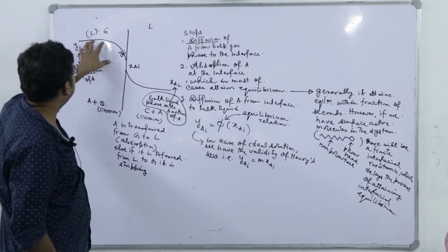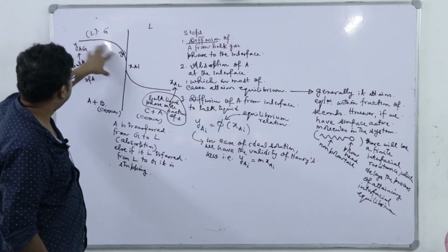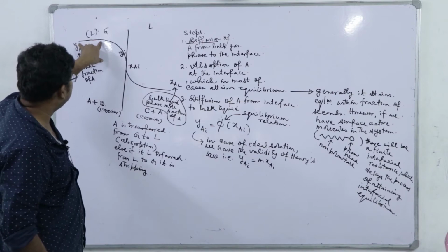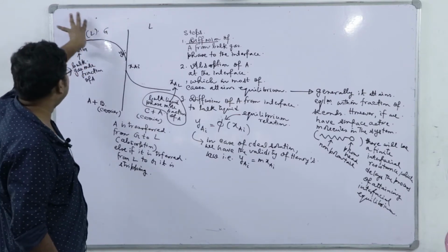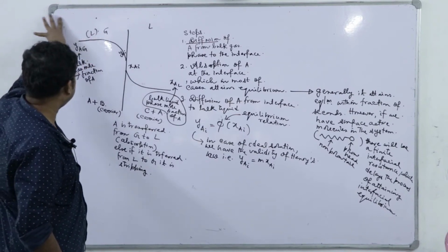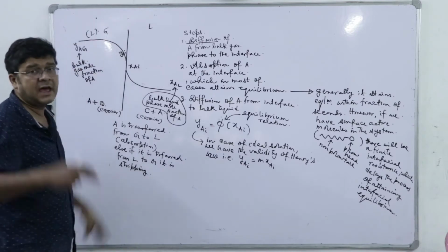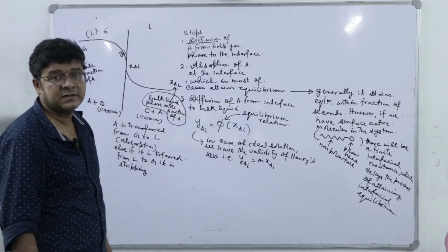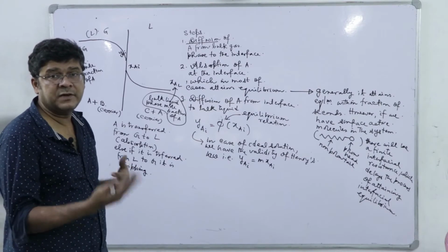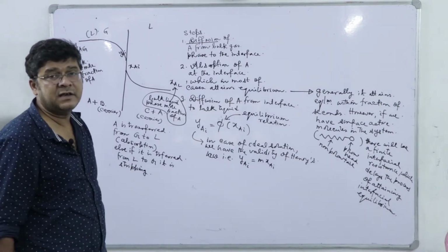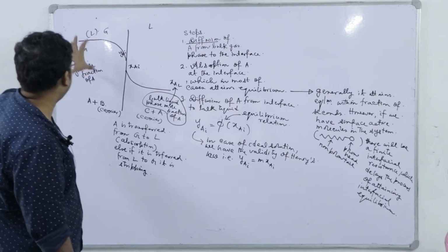So, here we need a very low driving force, because the resistance is insignificantly lower as the local Reynolds number towards the bulk increases, and we know from our previous discussion that the mass transfer coefficient has a monotonically increasing trend with Reynolds number or the turbulence.